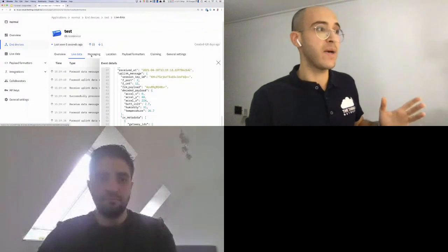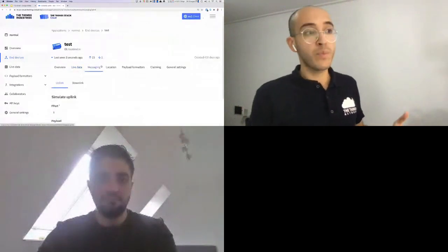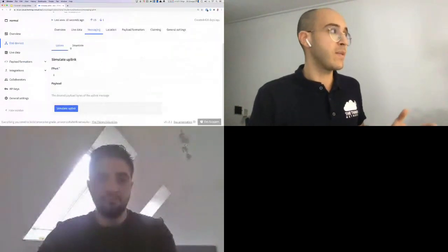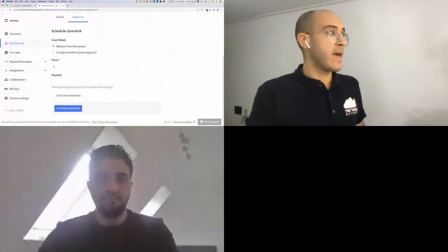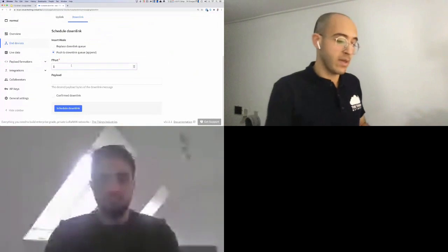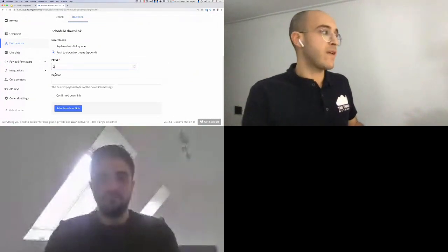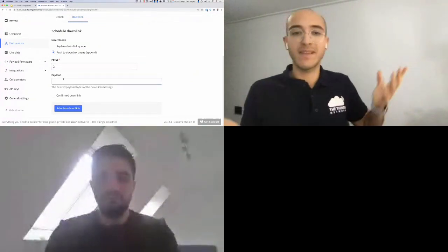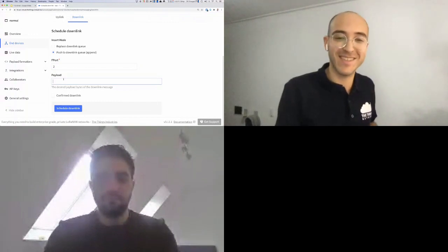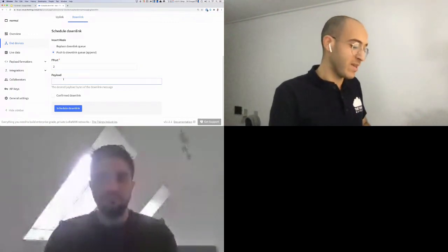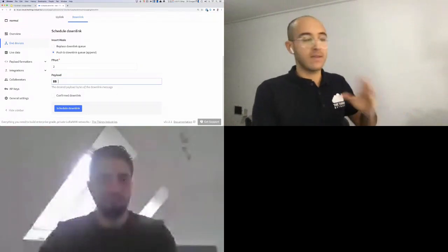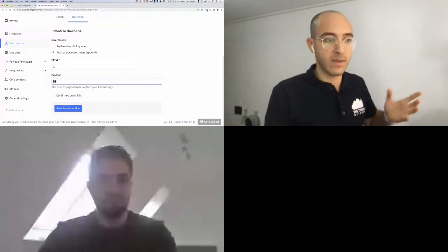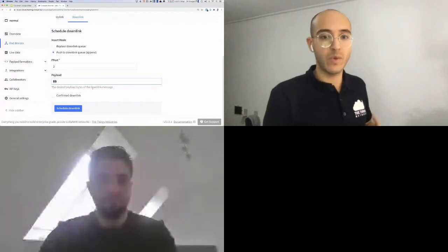So let's send it a message. We have an onboard buzzer that basically helps us with that. If I go to downlink, I'm going to push some decoded value, and I made it BB. In hexadecimal, just BB for buzzer. Basically, I'm telling the device that the operational voltage is not too good and we want to change it.